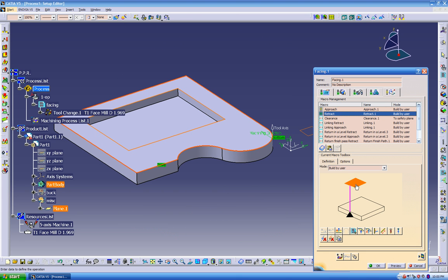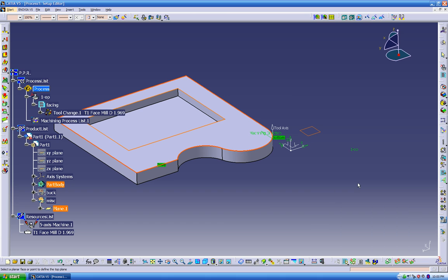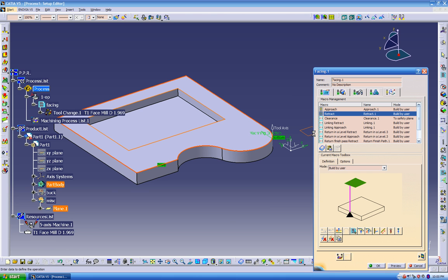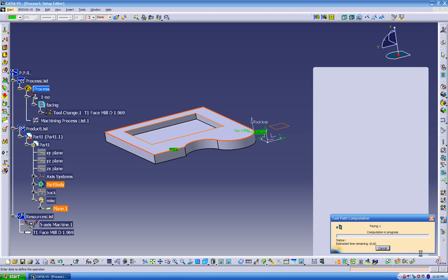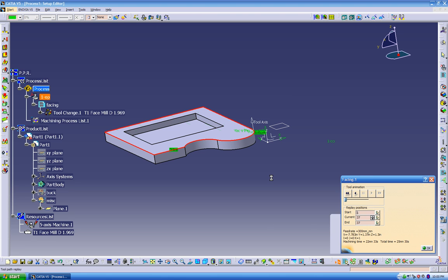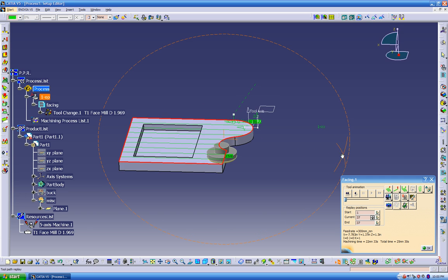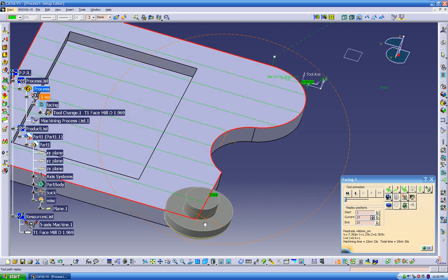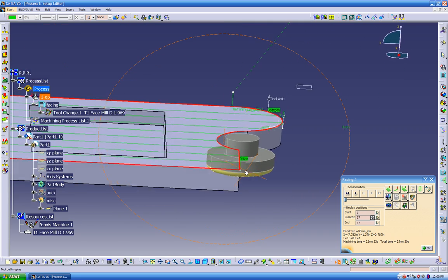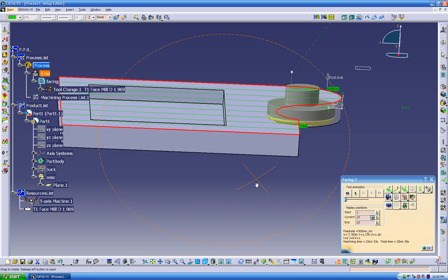And then retract, I'm going to do the same thing. Once the tool goes around, it's going to retract from here and go up to the clearance plane. So I click on the plane, then click on the clearance plane. Then you come down here and we do toolpath replay. So this is our tool. But see right now the tool is right on top of the part, and I don't want to plunge right on top of the part, I want to plunge outside.